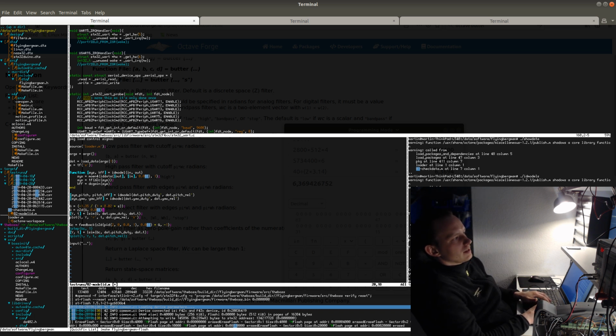And we can easily approximate this. For example, we start with a time constant of 1 and a gain of 1. Then we convert this function to a discrete function and simulate it with our discrete input data, which in this case is the yaw duty cycle.